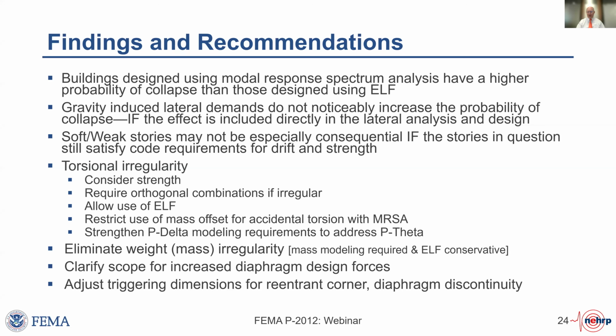Gravity-induced lateral demands are important in system performance, but as long as you consider the effect that the gravity demands have on your performance, you'll not have worse performance. If you ignore the fact that you have sloping columns or that you have sustained lateral effects, you will end up with a poor design.